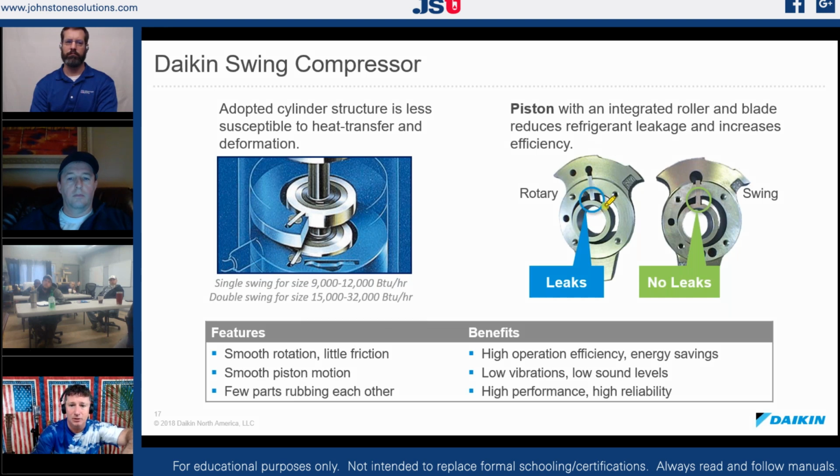compressor, it has a crank that is just turning this center cavity. It's compressing its vapor across the outside of the cavity. And then as it enters, it is using a blade that has a spring up here to keep force on this blade so that it maintains traction against the center of that compression device. I'm not even sure what they're calling that compression side of that. So we're going to constantly have friction across that point.